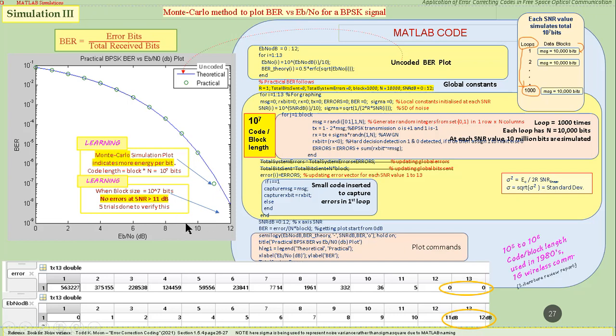This little difference means there is some change of SNR. More SNR, fewer errors. So SNR plays a key role here to reduce errors. And at larger SNRs, the errors are totally killed to zero, no errors happen. So if we increase the block length, we'll be able to see errors. And if we change the transmitter power, this graph will shift here and there.